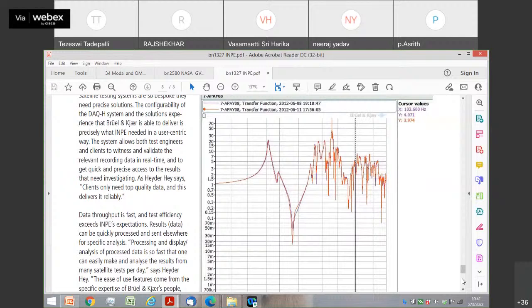It's very difficult for me to just sit here and say what could be the problem, but these are things that you could look at. You could mount 2 sensors very close, and run both of them to independent channels of the DAS, and then look at the data simultaneously and see whether any data is vanishing during the test.